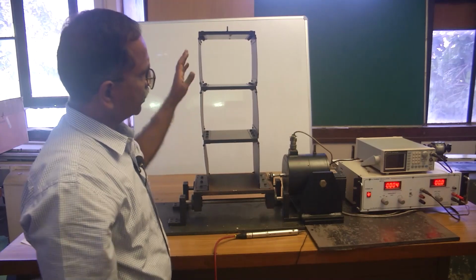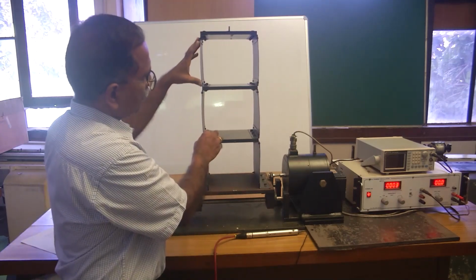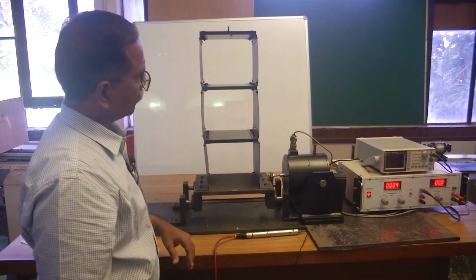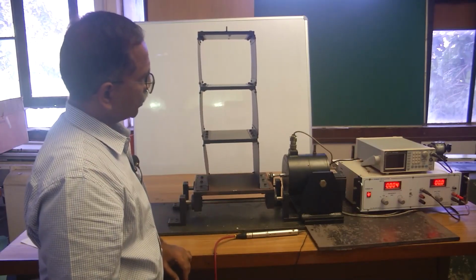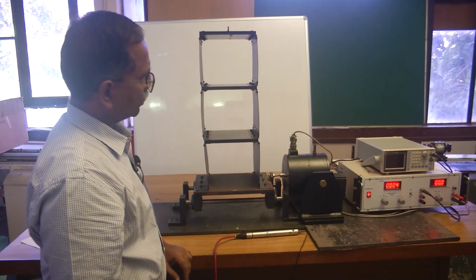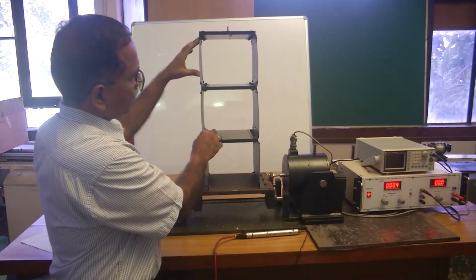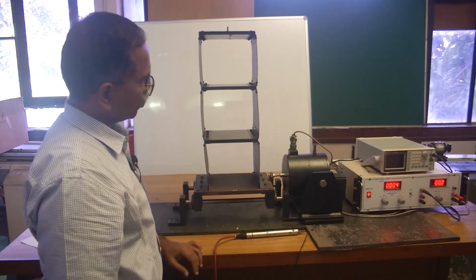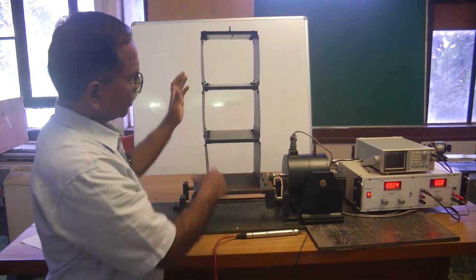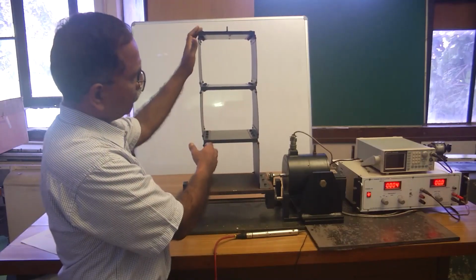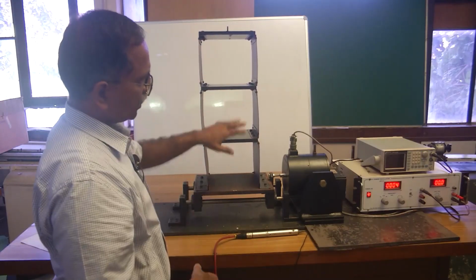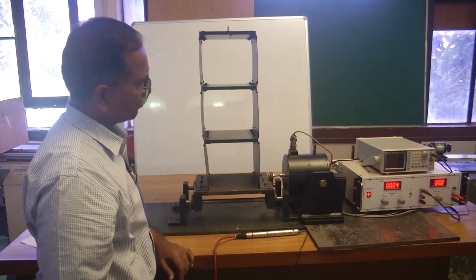Now, in this case it has definitely moved in the first vibratory mode, the mode 1 displacement pattern. The mode shape number 1 was evident here, and you can actually calculate the mode shape based on the numerical values of the masses and the stiffnesses of these plates.